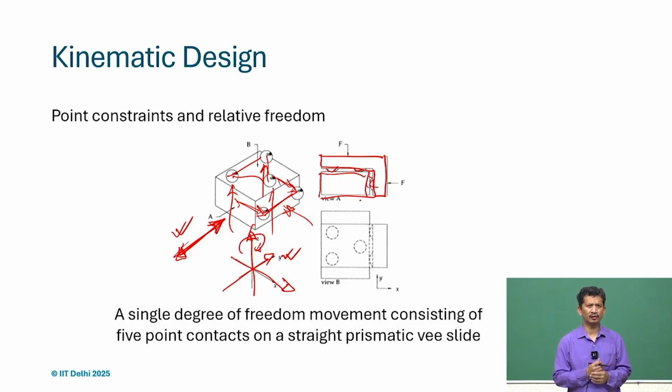For instance, in SolidWorks we call it mating. What we have to define is the surface and the ball contact, so that it is only a point contact. When we define these 5 contacts, we realize that we can just move along the axis defined here.